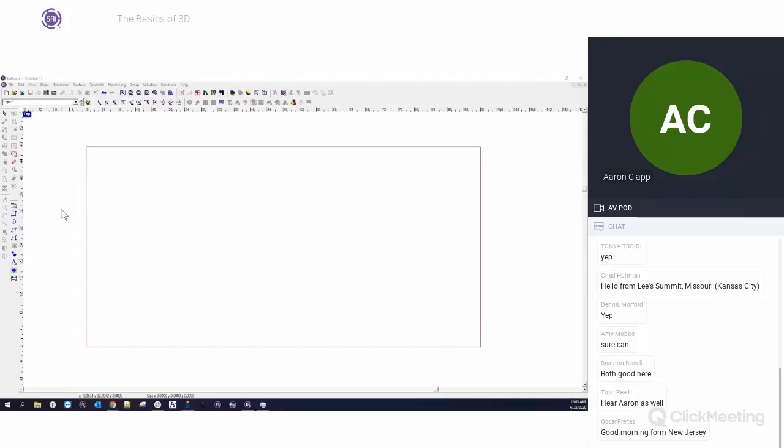EnRoute knows what it is and can display it to you, but it doesn't know how to toolpath that particular object. The things that EnRoute can toolpath are reliefs, though. And by default, reliefs are always yellow in color, bright yellow. You'll see that here once we start getting into it.